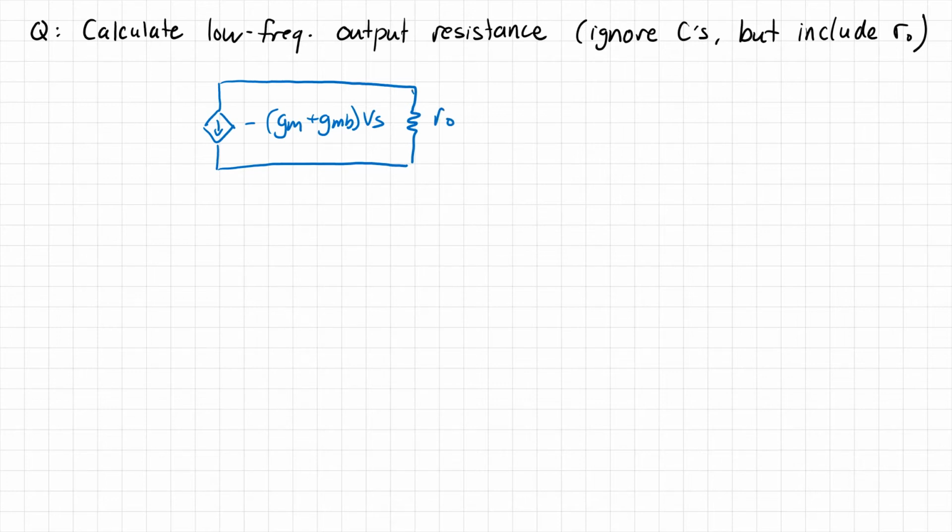And I'm specifically interested in figuring out what the output impedance is. The best way to do this is to apply a test voltage and measure the resulting current, I test. Okay, so let's complete the rest of the circuit here, ignoring all those capacitors. This is just RS. The input source is open circuit because we're doing this via a superposition-like analysis.